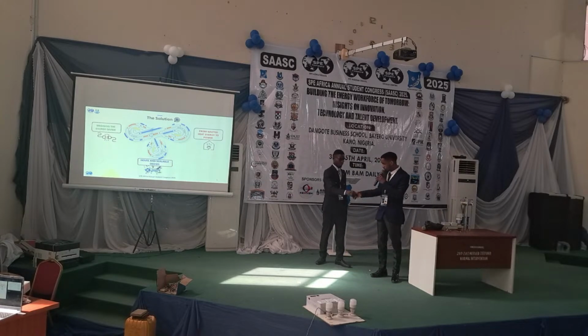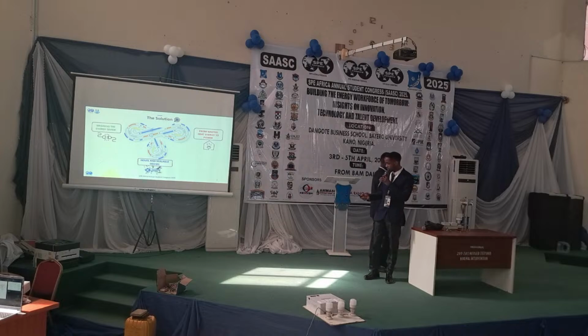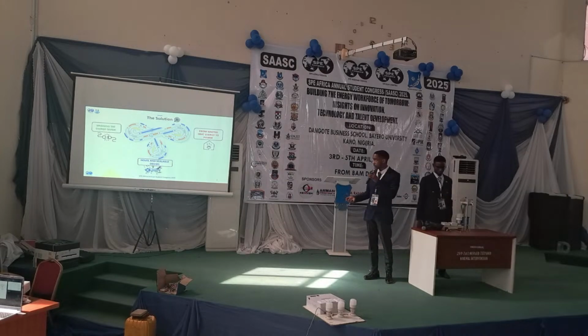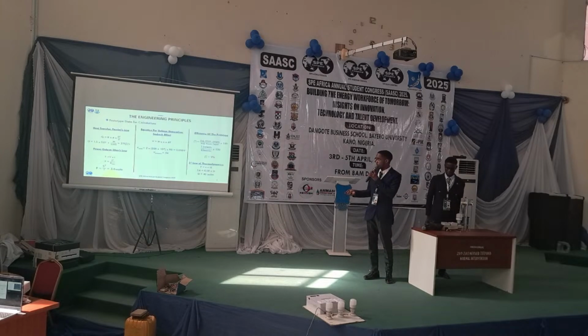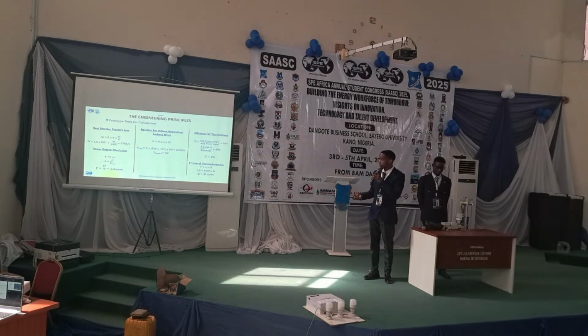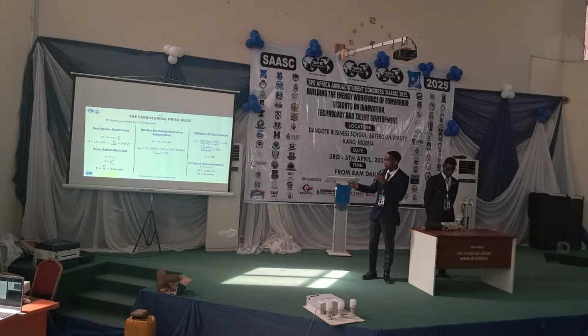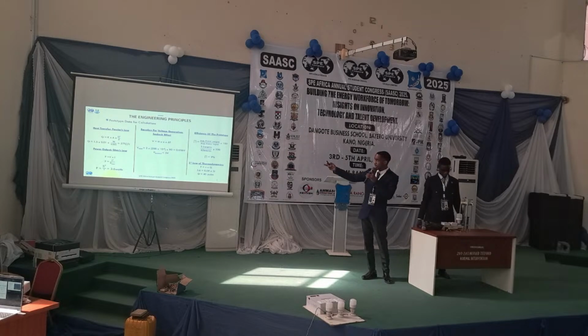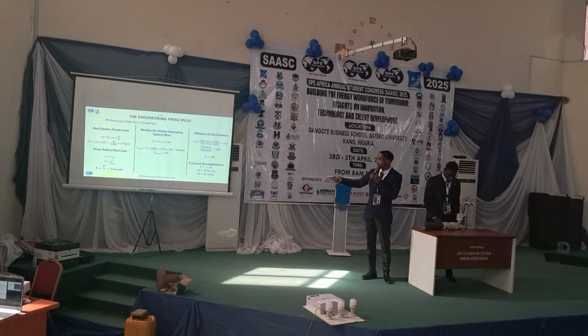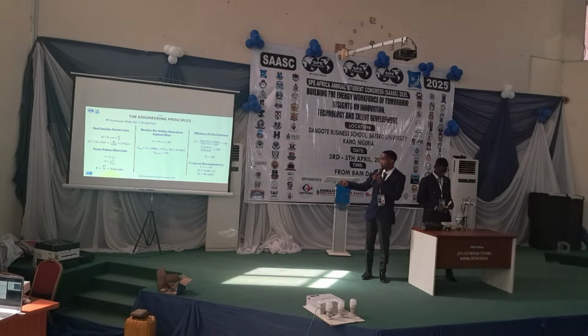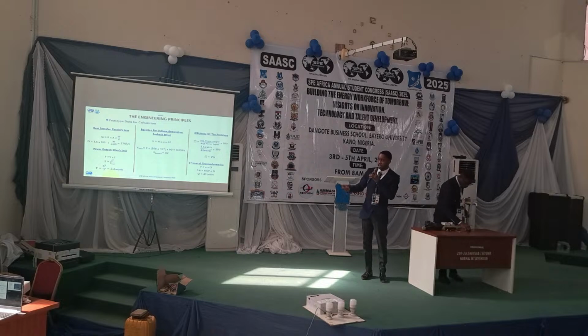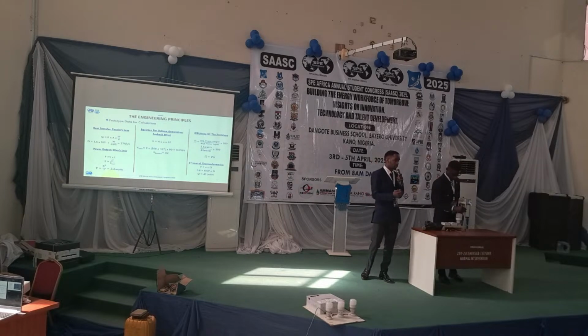Okay, my name is Unibe Fraser, and quickly we'll be looking at the engineering principles that led to this design. So first we have Fourier's law, which is our heat transfer, and then our thermoelectric generator, which is built with bismuth telluride, with a conductivity of usually 1.5 watts per meter Kelvin. And since we're using candlesticks, the area in contact with the heat is about 0.01 square meters.